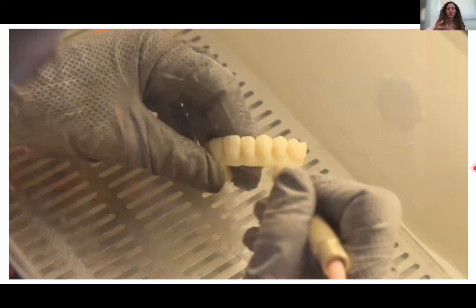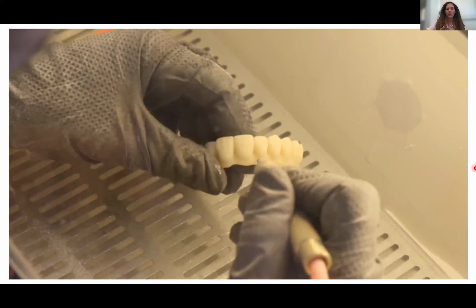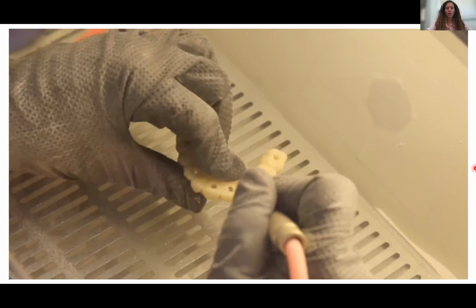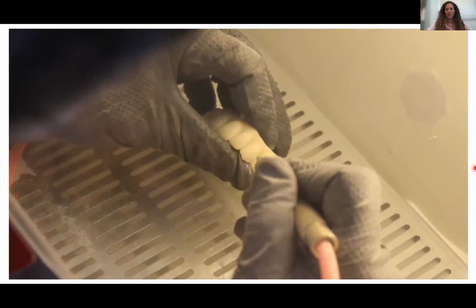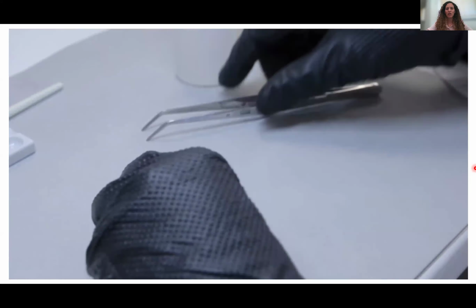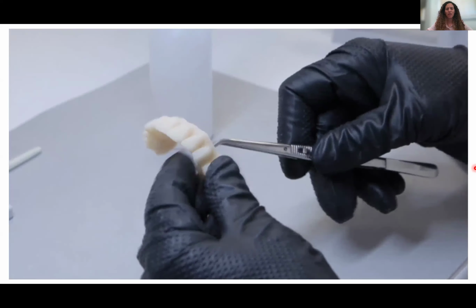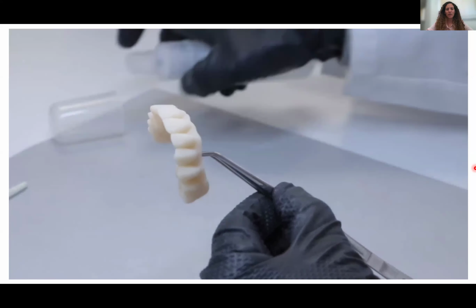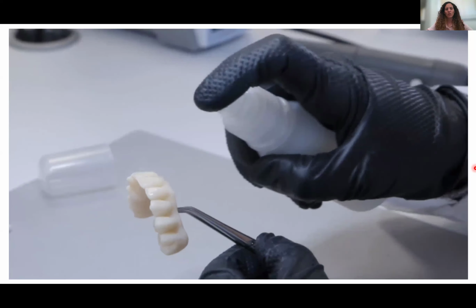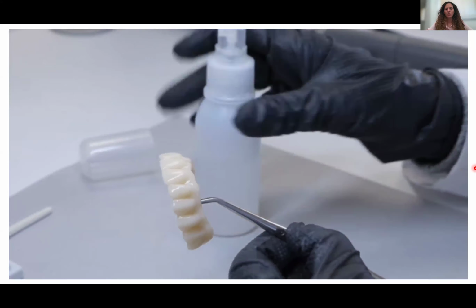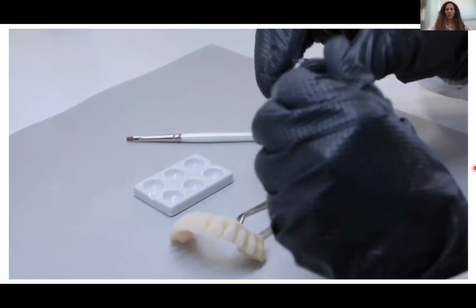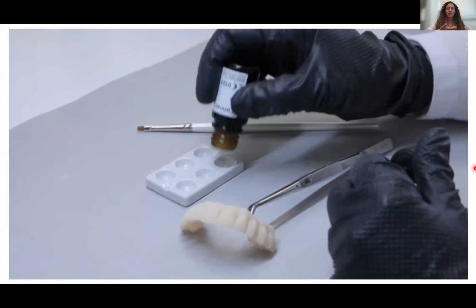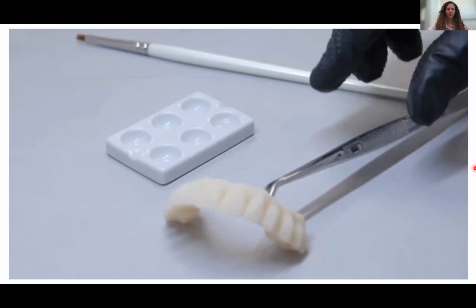When we have already finished the milling, remember that we don't need any thermal process. We can continue with our finishing protocol for the prosthetic. We don't need any sintering process. We don't need any intermediate. We milled and finished our processes. We sandblast with aluminum oxide, 110 microns, 2-3 bars of pressure. Then we clean with alcohol, not water or water steamer, always with alcohol.